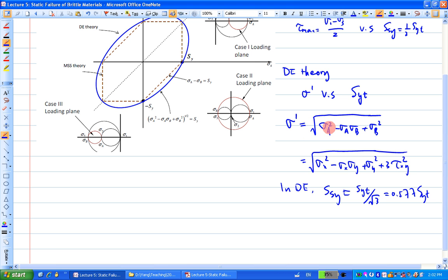But usually what we deal with is plane stress. So these two equations here are how you calculate von Mises stress based on the plane stress. For example, if you know your principal normal stresses for the plane case, A and B, then this is the equation. If you have the state of stress for the plane stress, you can use this equation, right? Either way is fine.